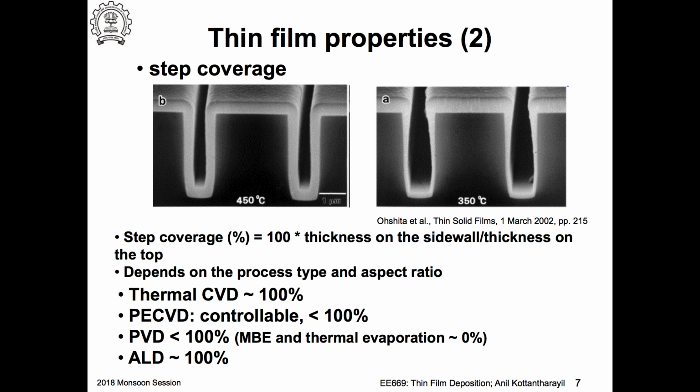In electromigration, the flux of electrons flowing through this material pushes the atoms, and then the atoms will start to migrate. That's called electromigration, and at some point of time you would have discontinuity in the film.